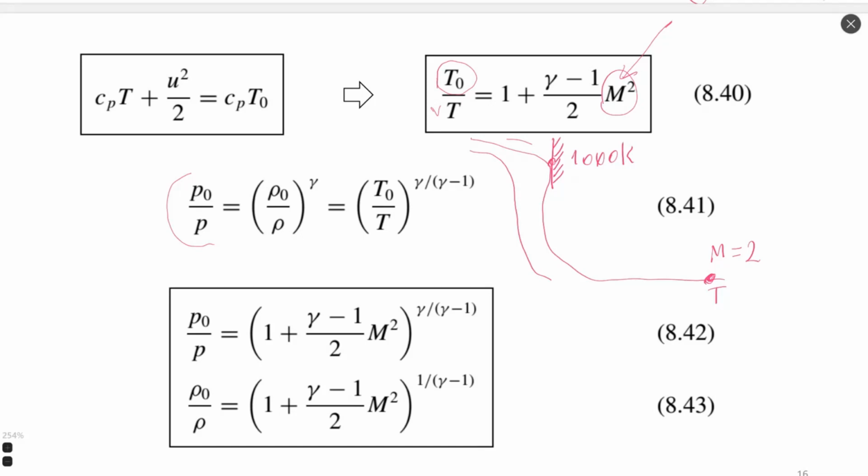But as you will see in future calculations, the reference point cannot be just the stagnation point. It can be any point where you know flow properties. We can always make a transformation from the stagnation point to another arbitrary point, and we can calculate the whole set of thermodynamic properties according to these functions. A very powerful tool. Probably these equations are among the most important in isentropic flow. They relate velocity in dimensionless form and thermodynamic properties of the flow.